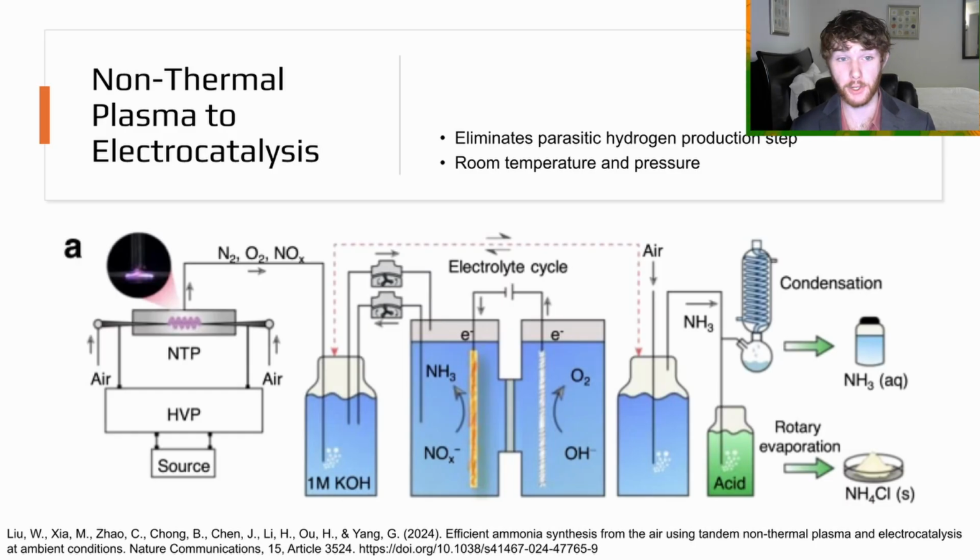Once the ammonia is produced in the electrochemical section, that is then bubbled out and then recondensed, similar in the way to the Haber-Bosch process, where the captured elements of the catalytic reactor are cooled and then refrigerated. There would likely need to be a similar step here. I think something of interest is the differences between this system and an actual pilot system or a full-scale chemical process would be essentially that step.